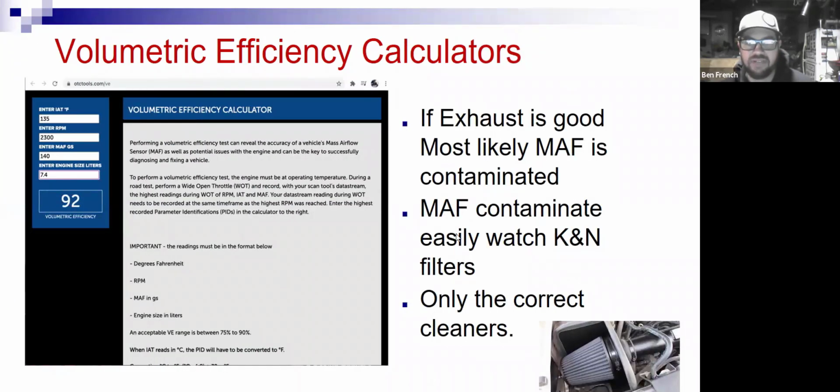So there's that table, and we talked about those contaminated mass airflows. And I also said, hey, be really wary of these aftermarket air filters. A lot of these air filters, in order to work properly, you have to oil the filter, and the oil on the filter will wick off and get stuck to that hot wire of the MAF and throw off its readings. Even stock paper filters, I find, little bits of paper will eventually rip off the filter and get stuck to the hot wire and contaminate that sensor. So contaminated mass airflow sensors are a real thing.